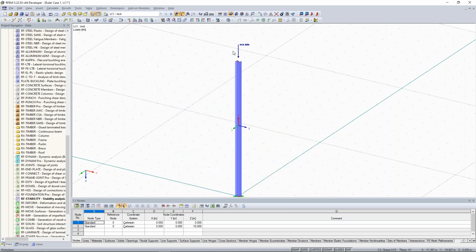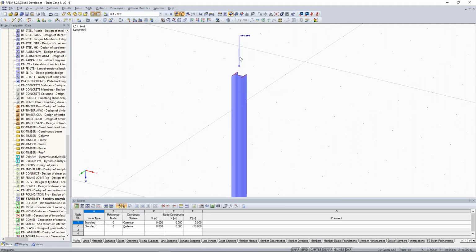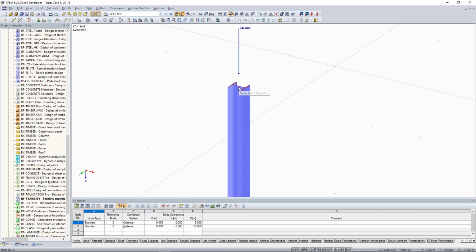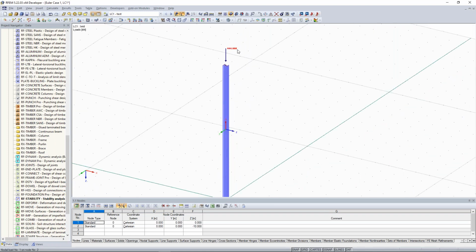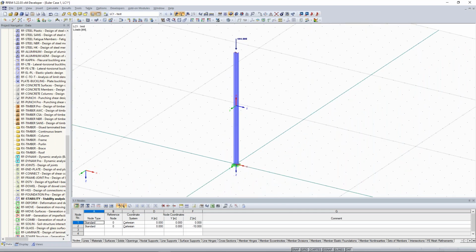Okay. So because of the loads, if I have some nodal load like here, it acts on the center of gravity or inflection point of the cross section. And this is also the reason why we don't have any torsion. So normally, in RFEM, the loads are acting on the center of gravity or inflection points of the cross sections. Okay, other questions?